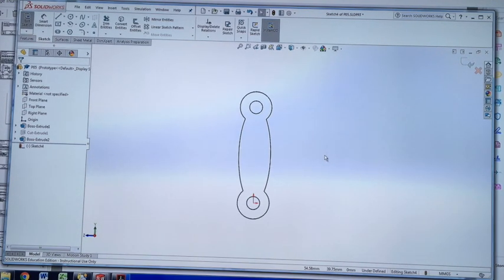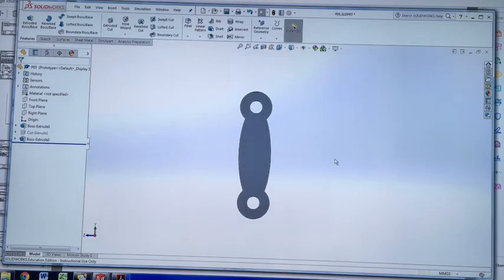and the text works on this example, okay, is the power on the laser is reduced. So instead of cutting all the way through the material, it only cuts a little bit of the way, all right? It won't remove a lot of material, okay? It won't create an area that's got a depth to it. It's basically just cutting a line, but instead of cutting a line all the way through, it's only cutting it through 20%. So whether we cut it all the way through in our SolidWorks here or not doesn't really make a difference. The only bit it makes a difference for is how it looks on our screen, but when we export it,